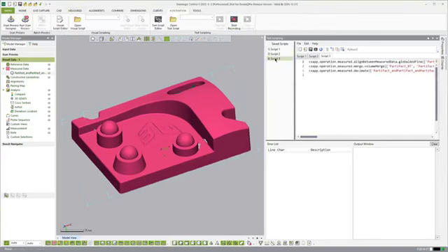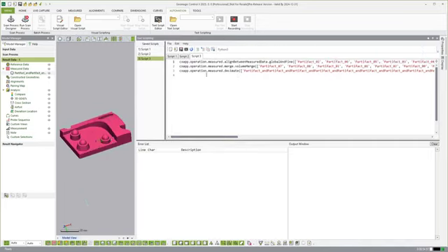So now that we did those three steps, we'll just come over here and say stop recording. And you see here that it built a script number 3. If we just drag this over, you'll see that it captured the fact that we did a fine alignment and it captured the names there. This one is going to be hardwired to those specific scans, right? It's going to look for these specific scans and then merge them.